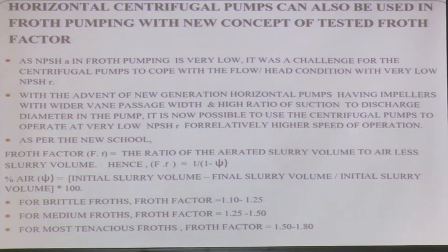That was a challenge. With the advent of new generation horizontal pumps having impellers with wider vane passage width and a high ratio of suction to discharge diameter, it is now possible to use centrifugal pumps to operate at a very low NPSHR for relatively higher speed of operation.